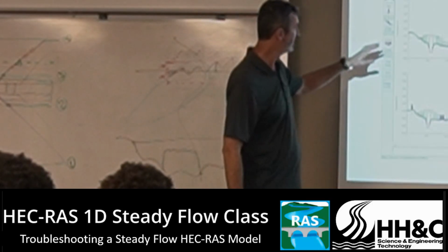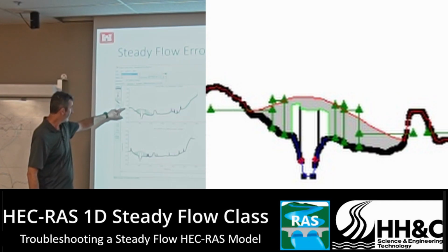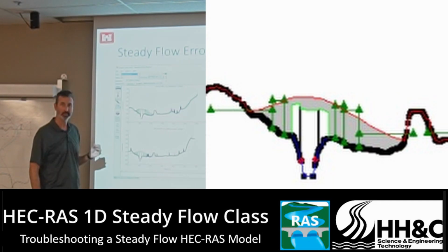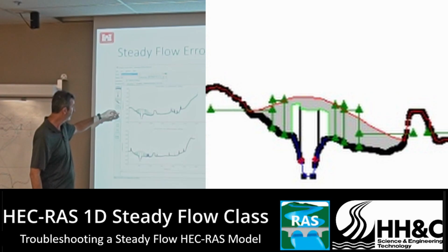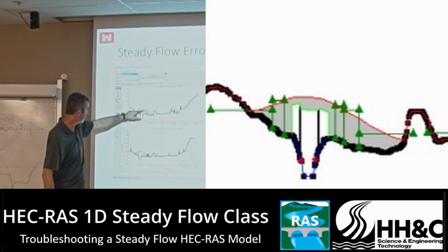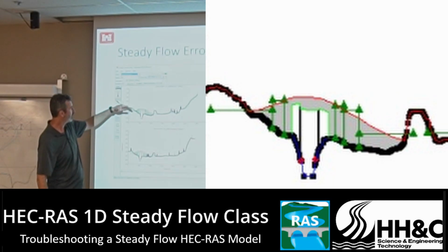Okay, so what is this graph? This graph has got some clues for that. And it shows you a red line. So the red line is going to be like, if there's weir flow, this is where it's going to be. I mean, this is what the program is going to consider weir flow. All the stuff above the red line. So here we got a red line right there, and over here, and so on. And this also is kind of, okay, so that's the weir line.